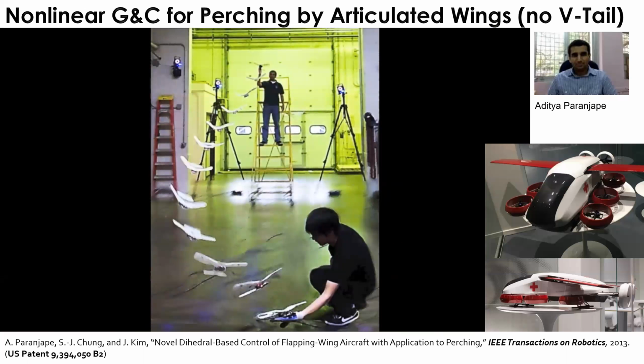This is the adaptive nonlinear control that incorporates the 3-dimensional flow measurements. For example, we measure the angle of attack, the sideslip angle, and also the forward speed using this 3-dimensional flow sensor. And we incorporate those measurements directly to update the estimate of certain aerodynamic parameters so that we can enable this smooth transition.